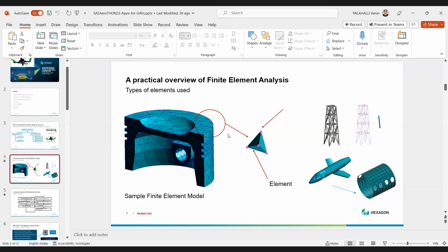However, when you come into something like a 3D body, like you saw a complex structure like an arm or something, and here you can see like a piston head, you roughly have equal dimensions in all directions. So in such cases, you would apply a 3D kind of a meshing approach. And what I was showing in my example is that I'm using the 2D approach only to mesh a top surface to define what I want as a refinement and then mesh the entire thing as 3D. So my entire structure is meshed in 3D, not in 2D.